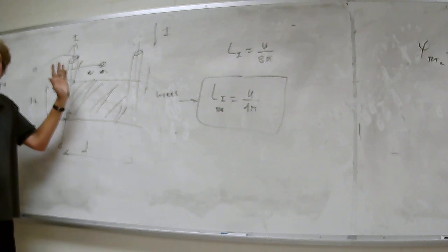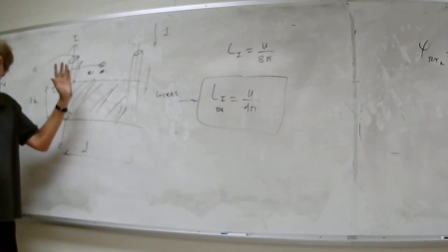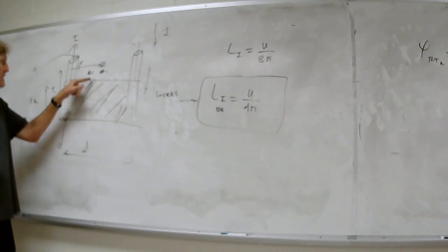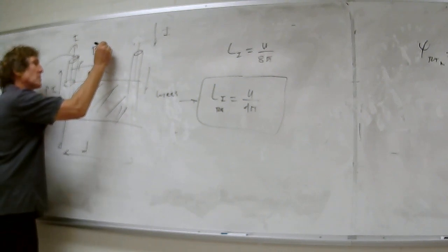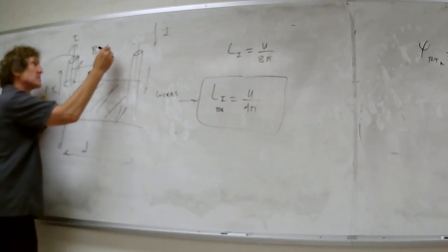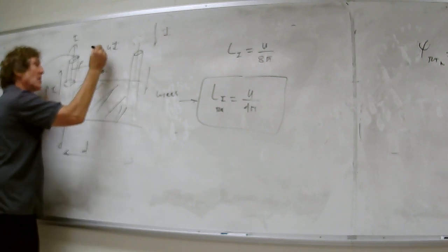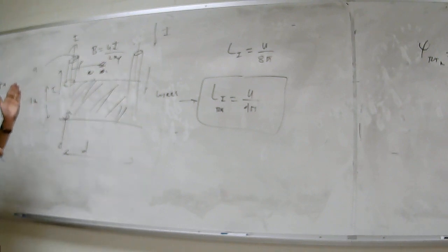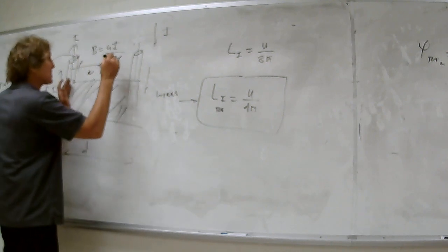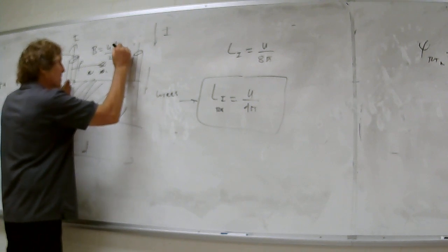Do you understand the reasoning behind this, everybody? You good with this, Chase? I'm going to find the B field from this wire. Well, this B field will be equal to mu times the H field, which is going to be I over 2 pi rho. Do you all follow me? It would be I over 2 pi rho if it was the H field. We multiply by mu and we get the B field. Do you agree with this, everyone? Yes. It would be into the board. It doesn't matter. You can call it A phi if you want.